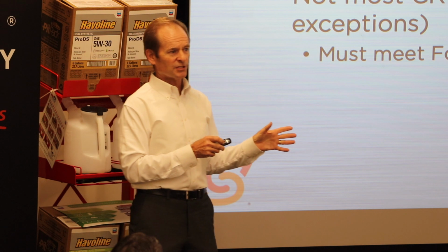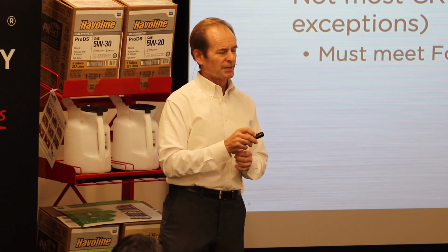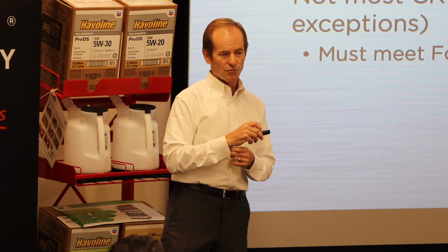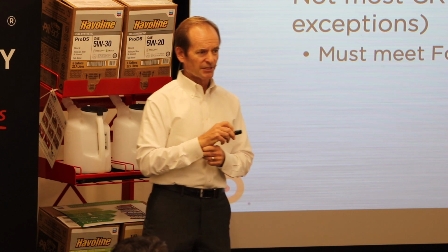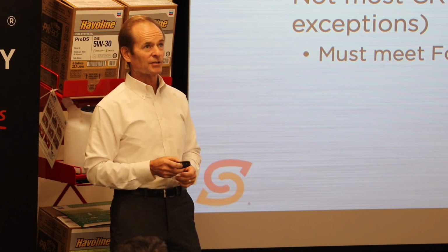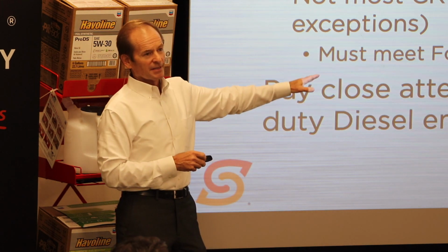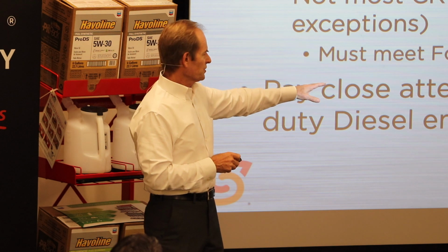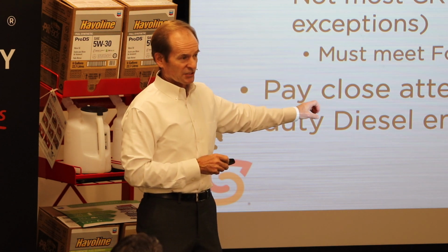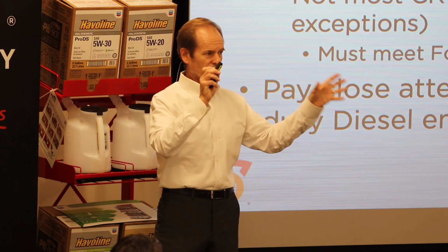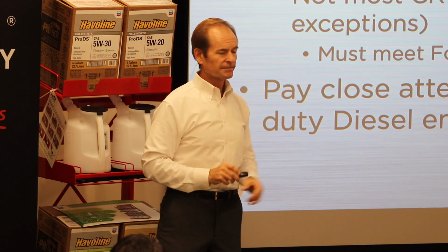Now, I don't know which diesel engines those are, but the note was that Ford's going to be approving the use of FA4 in the diesel engines going into the F-150 pickup trucks. The bottom line, pay close attention to what the OEM of the light-duty diesel engine says, and be aware that there are two new modern oils out there.